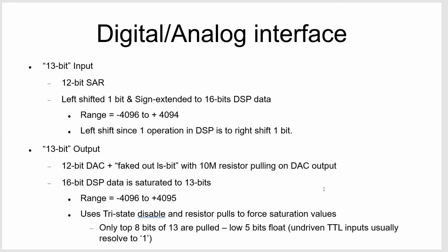We call this yanking, and so what happens is every so often when he wants to generate an extra 1 in the 13th bit position, he pulls on that part, and that makes the output of the DAC go up a tiny little half step from the other bit, and he kind of calls that 13 bits. So when does he decide when to yank it? Well, he has a little bit of logic in the schematic.